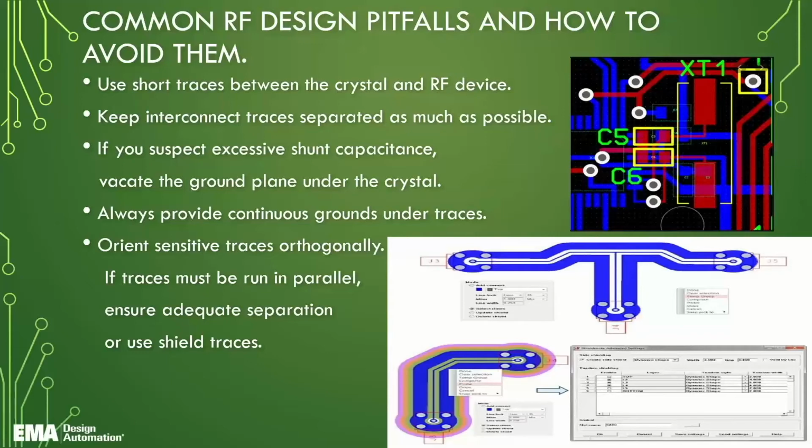That's good, except for the fact now you're going through a via, so you're adding inductance there. It'd be better to make room on the top for that. Come right out of there. I would not lay those down in a horizontal position. I would have C5 and C6 rotated, vertical, not horizontal, so that when I come out of there, notice that the C5 on the right, after it's coming out of the crystal, is now trying to go down between C6. And again, we're hitting that via, and that's not ideal.